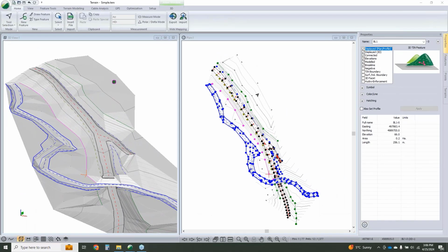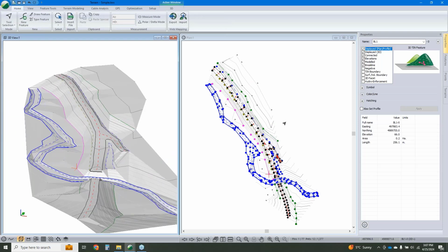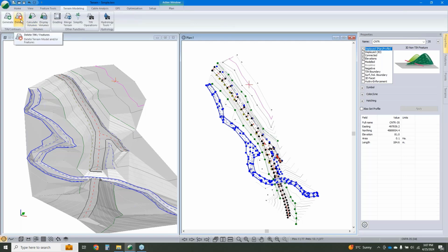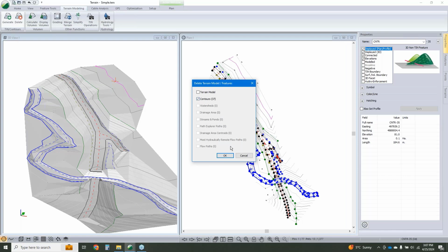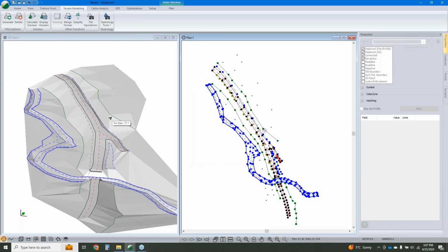Matt. All right, I will do some clicking around in the software. So to start, the same example that Erin was looking at, we'll just talk about the things she was talking about with the software open. So I've got my surface, we can see it. We've got our actual data that's used to create that surface. I've got some contours being drawn here. And just to reiterate what Erin was saying, the contours don't actually affect the surface that we're working with. So we can remove those contours and we could still do our design. The volumes in our design would be the same. It's just that the contours help add a little context for what our topography is doing if we're just looking at it in the plan view.